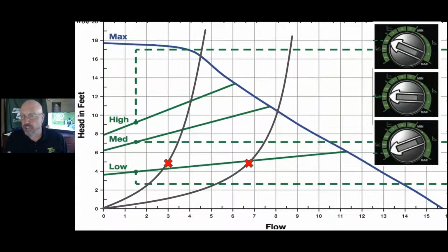And in some of these circulators that do have that learning mode based in it, it is designed for your TRVs, or your proportional pressure curves. And what it's going to do is learn which one of these curves to operate on. And it slides up and down and may even change those curves. So for example, if your design point, your operating point starts to slide up towards the maximum line, it says, all right, well, I'm getting towards the end here, I'm going to have to jump up a curve.